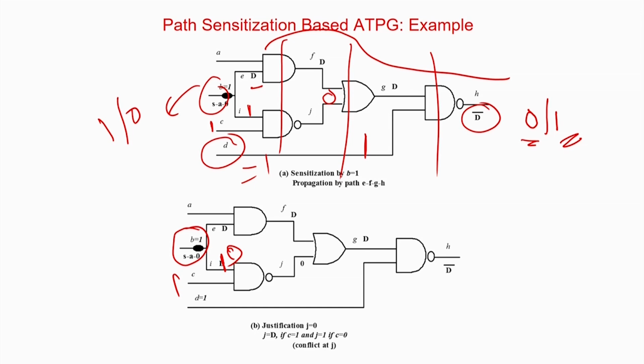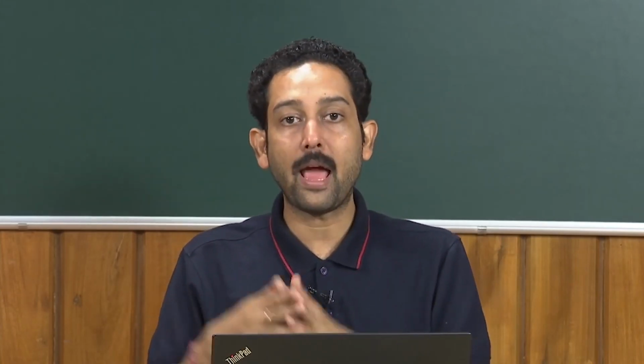I will consider adder as a block. I will consider maybe a multiplier as a block. This is actually called RTL level test. And we do not even go for stuck faults. We also go for some abstract level of fault models, like fault at the adder level, fault at the multiplexer level and so forth. Mostly they are motivated from the software point of view. So that will be the idea of how test patterns are optimized to handle large circuits.